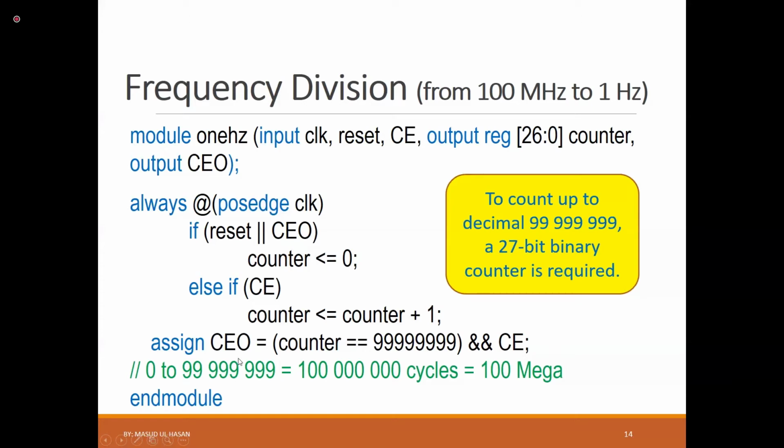In one project, two UCF files are acceptable, no problem, it will work. Second solution, if you are now an advanced user, not a beginner, you can put just 4 or 5 input outputs, whatever you have, in the same file of 7-segment display, and you don't disturb the other things. Just at the end make your own input outputs. This is the second way you can do it.